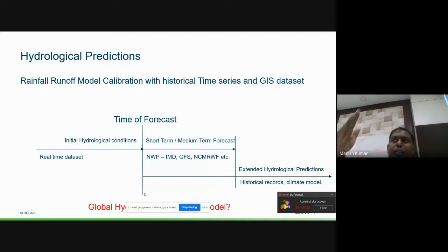So whenever there is a precipitation, obviously some of it will infiltrate, other will move as surface water as overland flow, and some of the water will be lost as evapotranspiration loss. Then the infiltrated water may get transpired, or it can percolate into the groundwater.